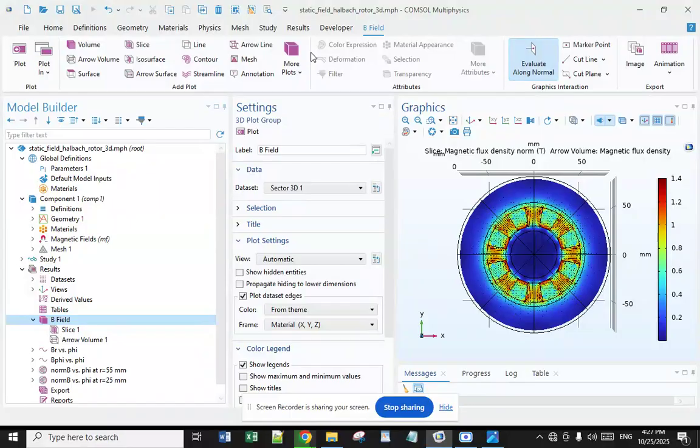And what are the applications? The advantages of one-sided flux distributions are twofold. The first one is the field is twice as large on the side on which the flux is confined. The next is there is no stray field produced, in the idealized case, on the opposite side. This helps with field confinement, usually a problem in the design of magnetic